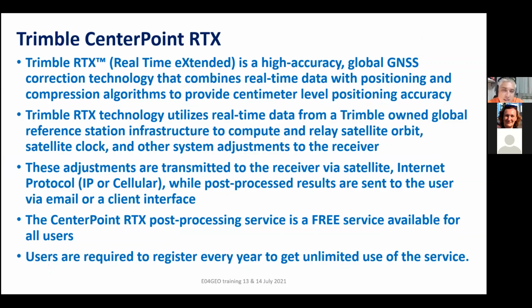It utilizes real-time data from a Trimble-owned global reference station infrastructure. So it does not use data from IGS, or primarily uses data from the Trimble-owned global reference station infrastructure to compute and relay satellite orbit, satellite clock, and other system adjustments to the receiver.